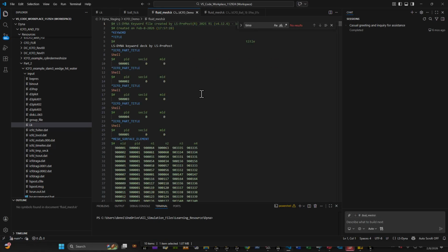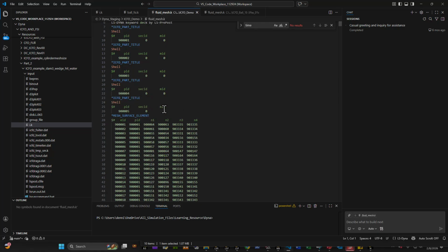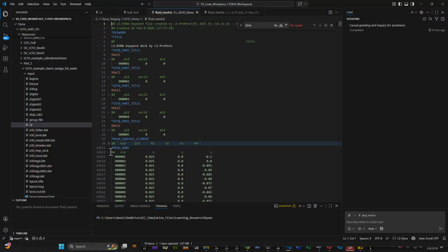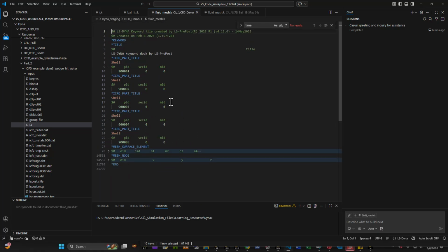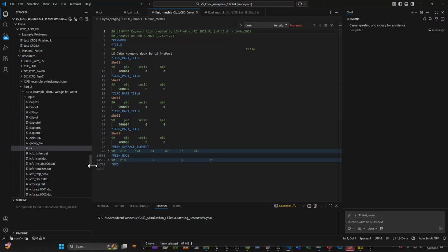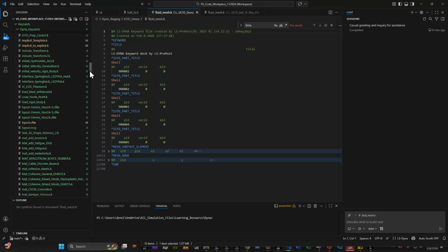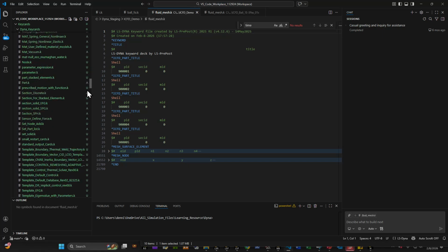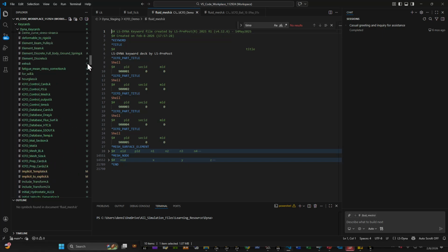Right, so if I open the fluid mesh, you can sort of see all I have are these shell bodies. I have nothing else, right? And then I have my elements, then I have my nodes. That's all I got. But this makes it a CFD ready keyword. Now what happens from here forward is that you can actually take this back to LS Prep Post to set up your model,